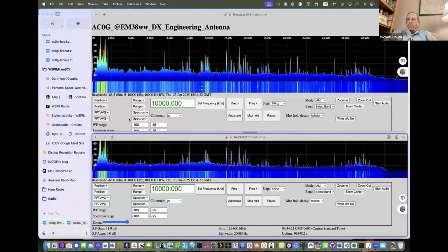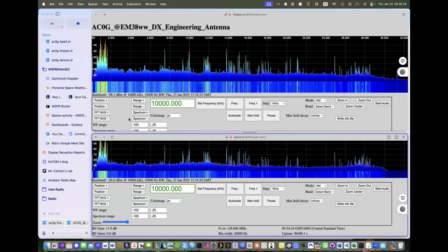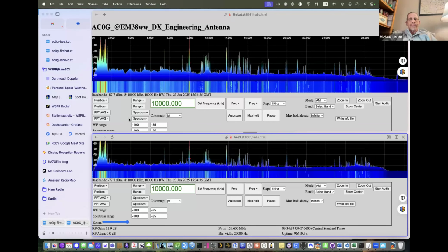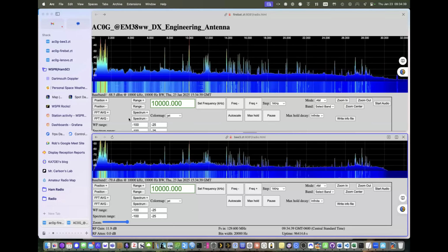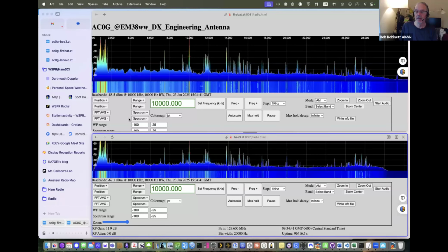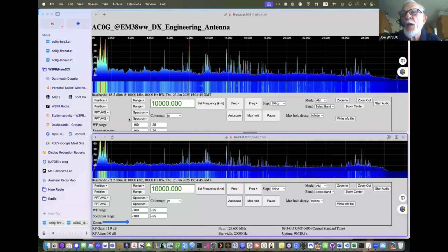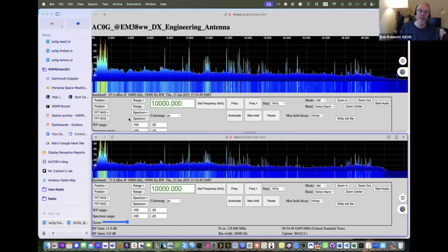It would be good if we identified specific makes that are quiet, because switching supplies can be quiet, but they have to put the components in. Right. And a lot of times they just leave them out. They're actually spots on the PC board. Yeah, I've had pretty good luck with the chargers that come with cell phones. Samsung seem to be reasonably quiet. That's a good point.